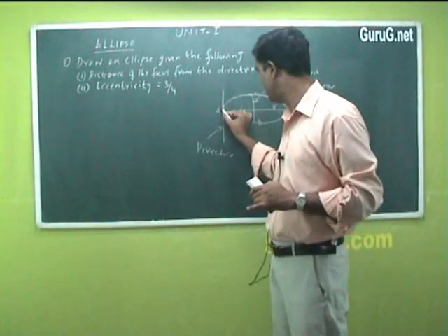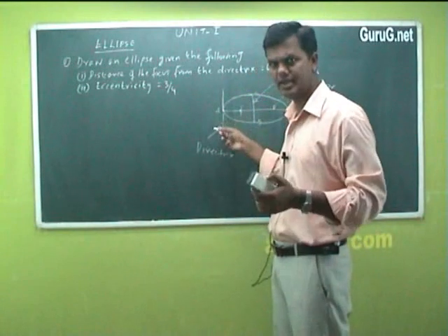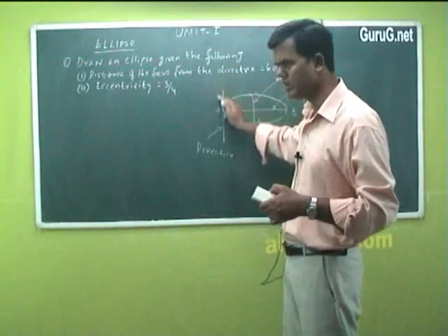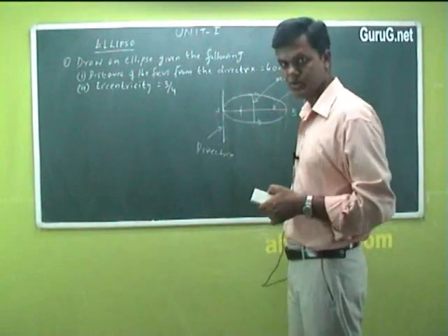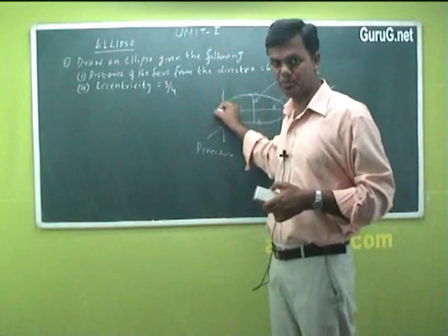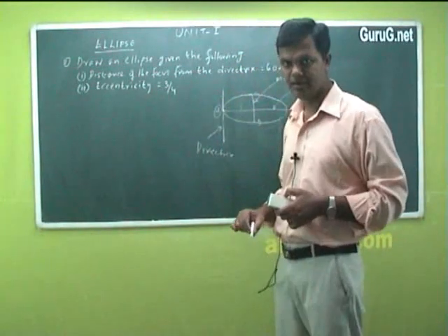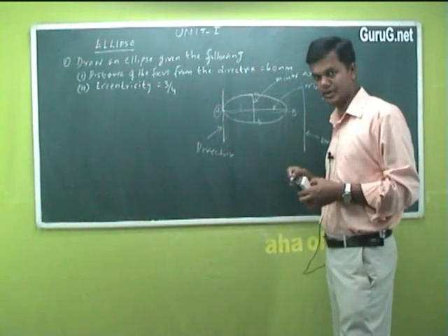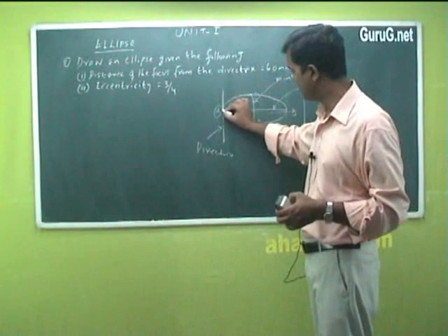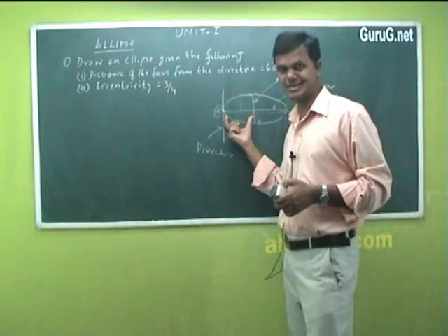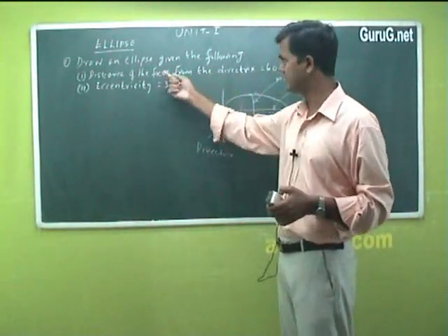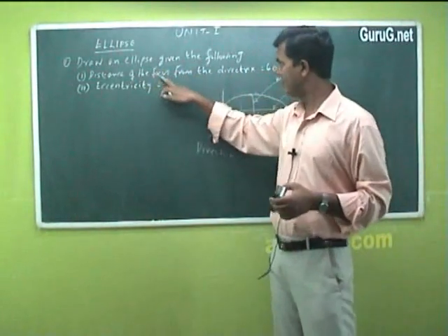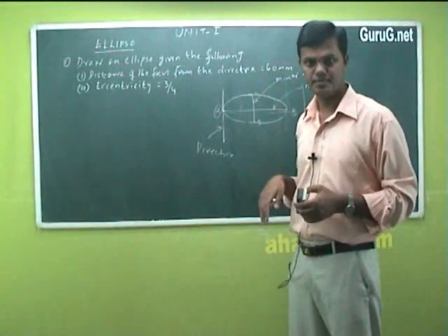So basically I require a distance from this particular point. This point may be anywhere; there is no confined length for this directrix. It's a normal perpendicular line. Anywhere on this directrix I can choose a point, say for example point A here, and I can draw an axis. That becomes my first step. Then from this point I should fix a distance. That distance becomes my focus, which is given as 60 millimeter. The distance of the focus from the directrix is 60 millimeter.